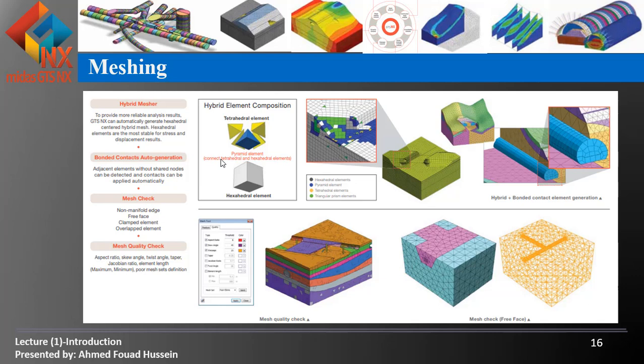Then you can include auto connect between faces and make a mesh check to check whether your meshing is good or not, and check the quality of your meshing, as we're going to check again later.